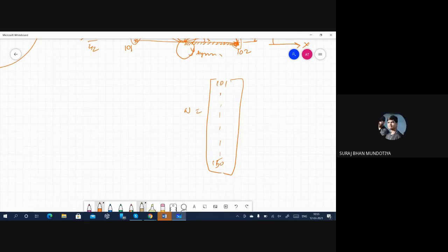And in compression, if there is a Bauschinger effect, some dislocations are working when you apply, let's say, stress in one direction. So dislocations are moving in that direction and they are getting locked and a lot of things are happening. When you reverse the direction of the stress, these dislocations were locked. For instance, when you have to go from Ropar to Chandigarh, that is the direction you are applying stress.